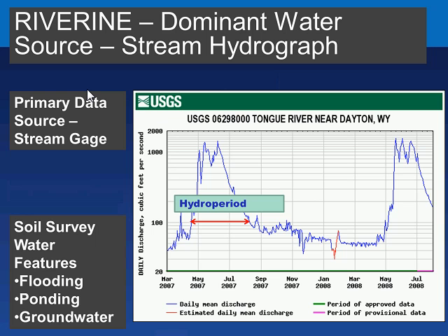And again, because of the snowmelt hydrograph, we have 2 successive years that show peak discharges around May going into June. It's also a good time to point out that if I'm fortunate enough to have good soil mapping in this wetland type or any wetland type, it's always a good idea to go to Web Soil Survey, take a few minutes, and print out the Soil Survey Water Features table.